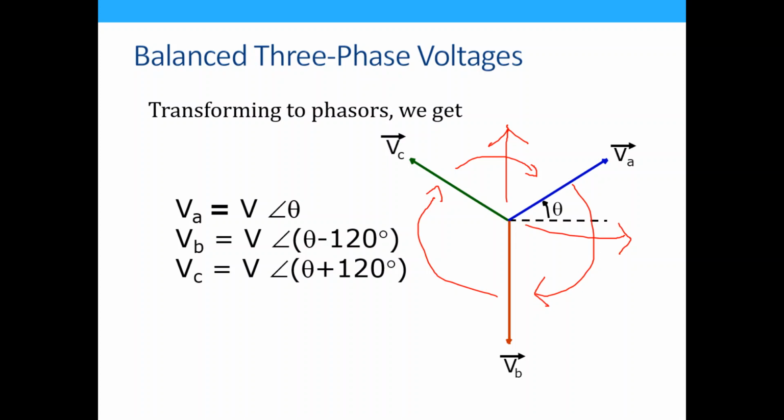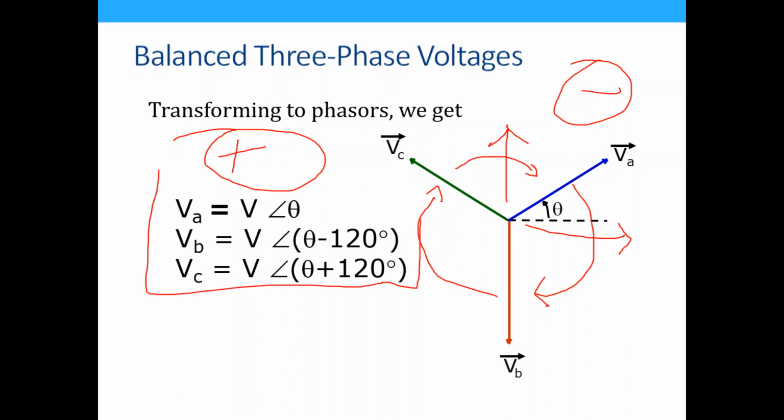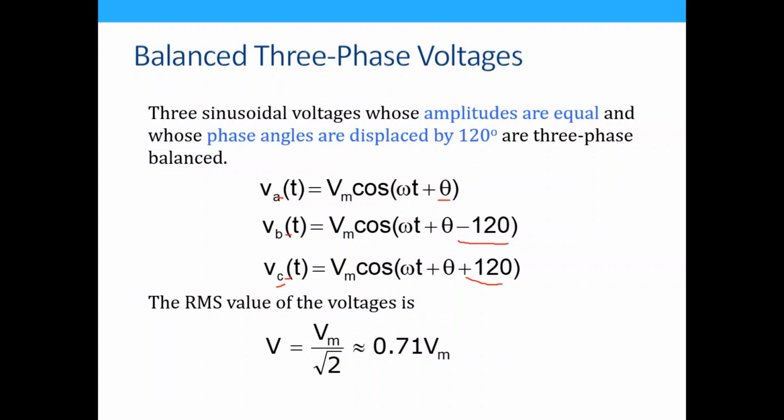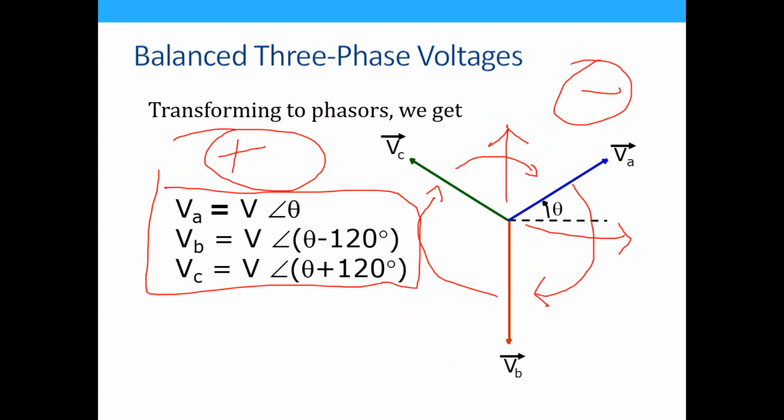We call this the positive sequence. Okay? We also have a negative sequence, which I will not discuss in further detail. Basically, it's just flipped around, where A leads C, leads B, leads A. So this is the positive sequence, and the phasor is this. Right? So these are the RMS voltages, and these are their phases. They are always apart by 120 degrees.